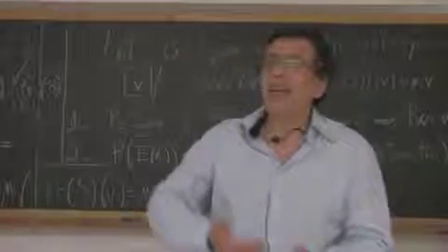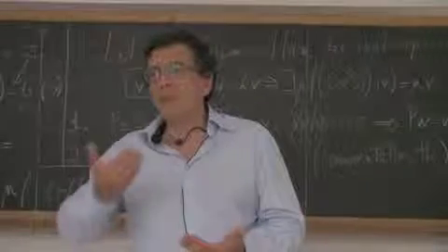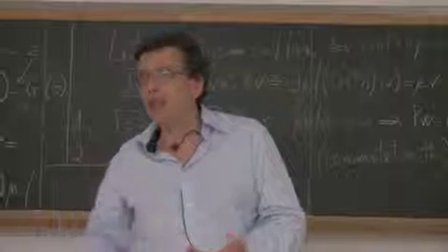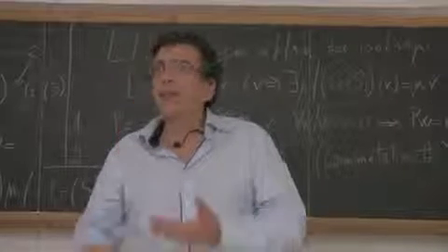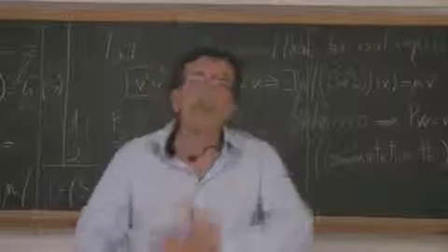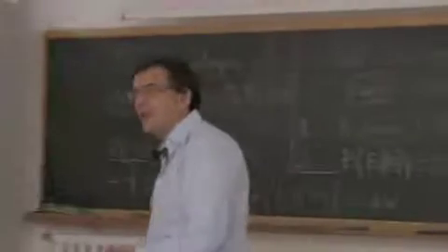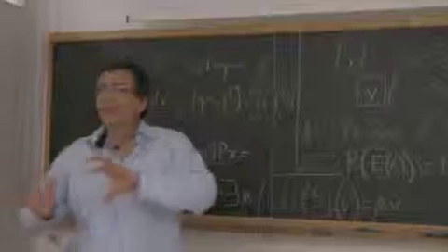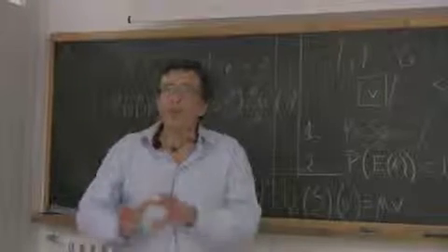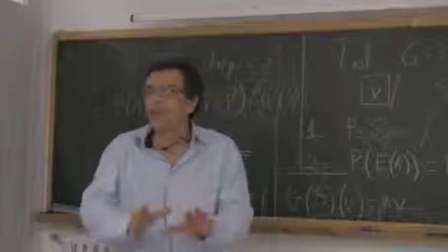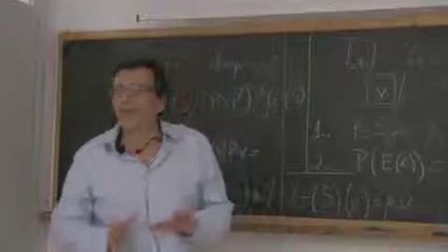And if you have an eigenvector of the symmetric part of the gradient of velocity, this eigenvector is an eigenvector of the Navier-Stokes dissipation stress. So isotropic constitutive equations are not changing the set of eigenvectors.